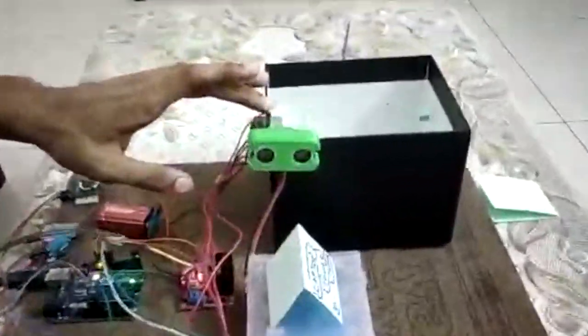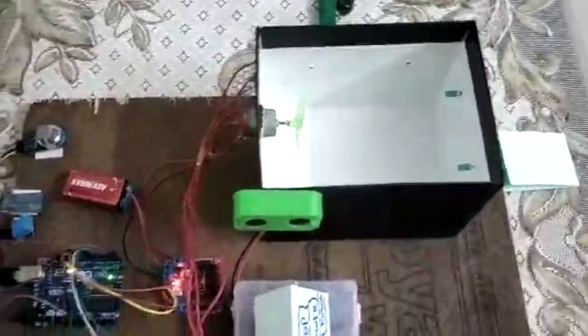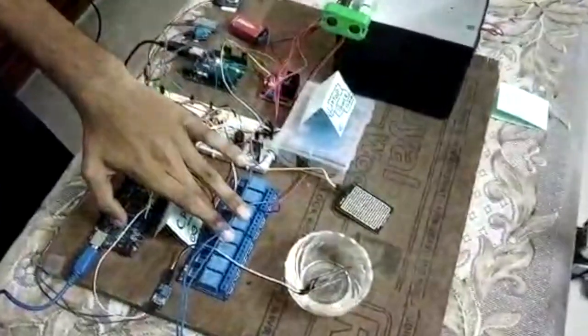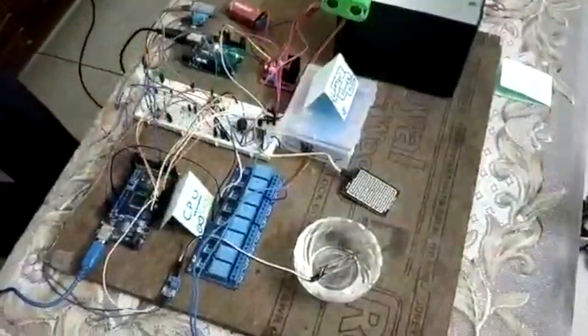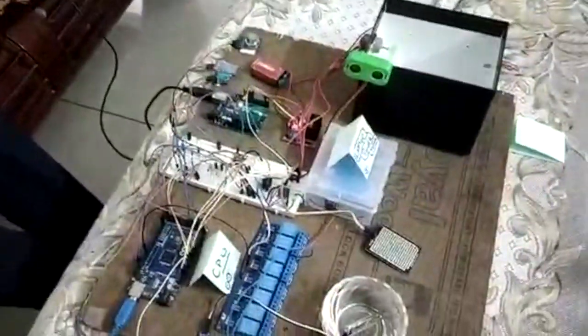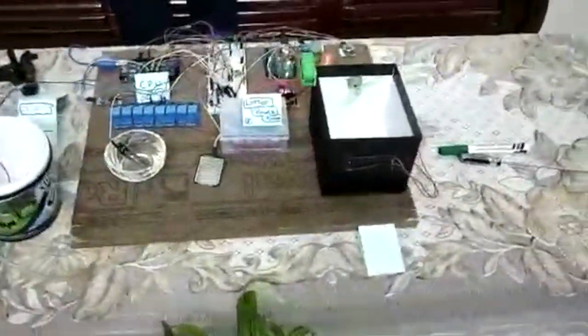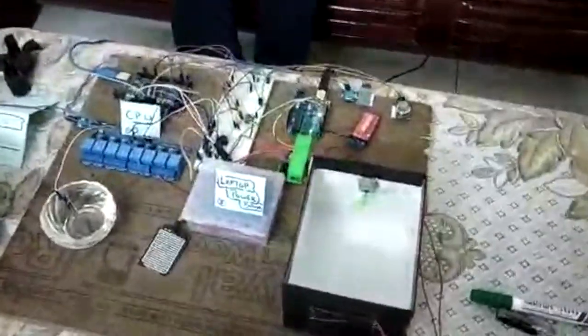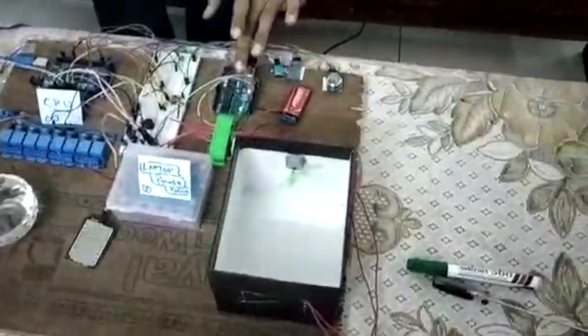smart. So what we have done here is I have a simulation of a house where we have lights, fans, and these are low powered devices. But in the same manner we can use Arduino to send low voltage signals, and that can be sent to a relay module which can connect to high voltage signals, and these relays can be used as magnetic switches. So you will not have any more switches in your house. These are electrical switches which work on the basis of magnetism. So these magnetic switches turn on and turn off high voltage devices as they get signals from our Arduino.